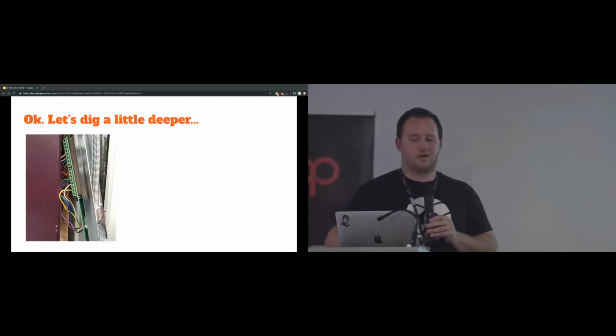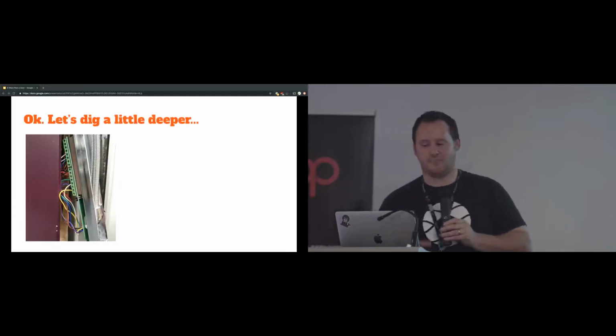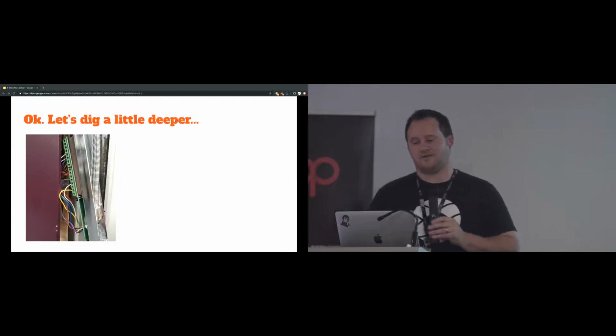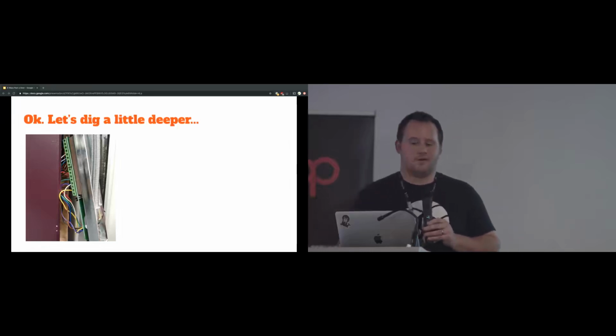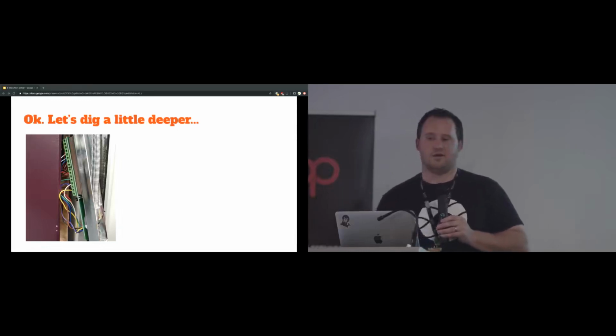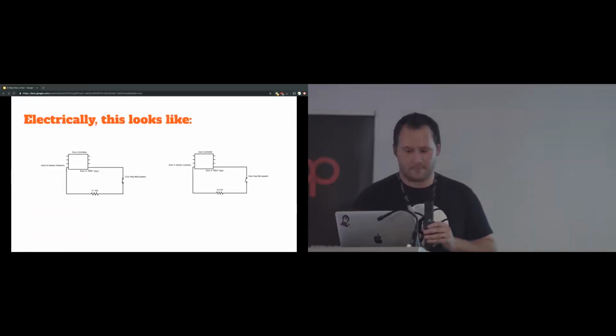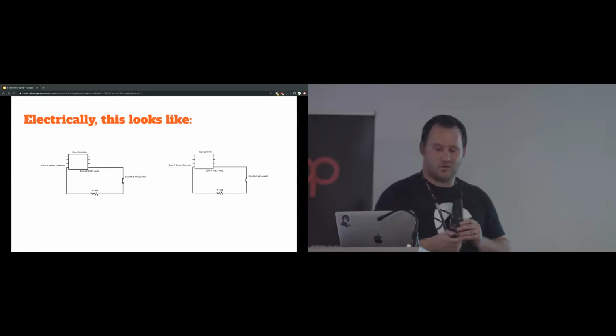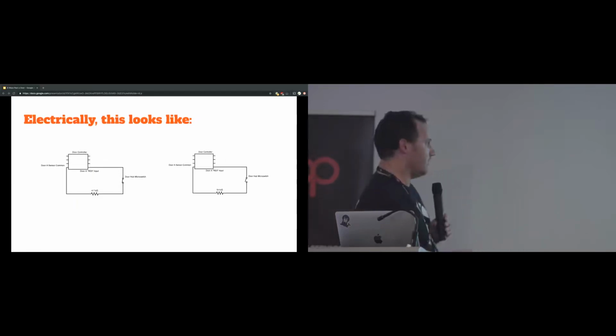And there's actually this extra little bonus bit of circuitry that's installed in the back edge of the door, and this interfaces between the wiring of the door controller and the wiring inside the mortise. And interestingly, while the mortise itself does indeed go short circuit when you turn the handle, this little PCB kind of changes things up a bit by introducing a couple of resistors. So when the handle is turned, which is going to be that one,